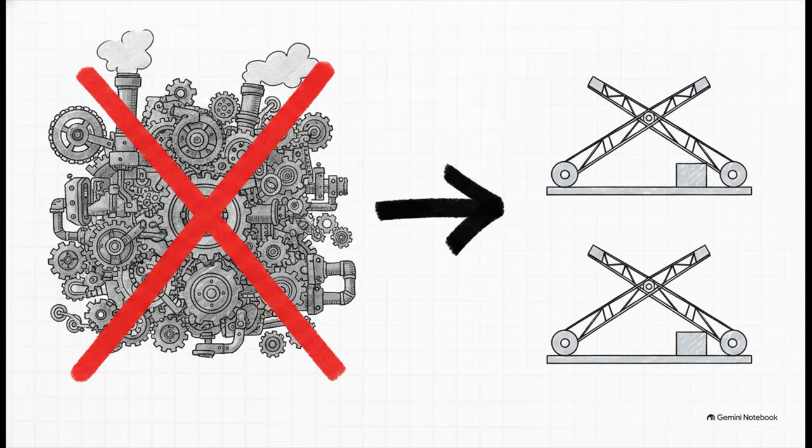And here is a ridiculously brilliant hardware trick that saves massive amounts of silicon real estate. In a neural network, you constantly have to multiply inputs by their weights, but physically building a multiplier circuit on a chip takes up a ton of space and power. However, because our inputs for an XOR gate are strictly single-bit binary, they're literally always just a 0 or a 1, engineers realized they don't even need multipliers.